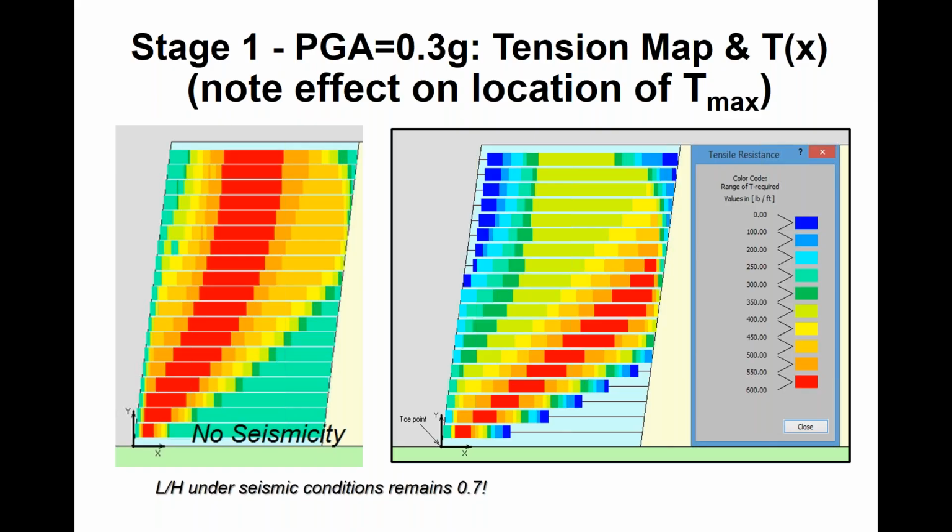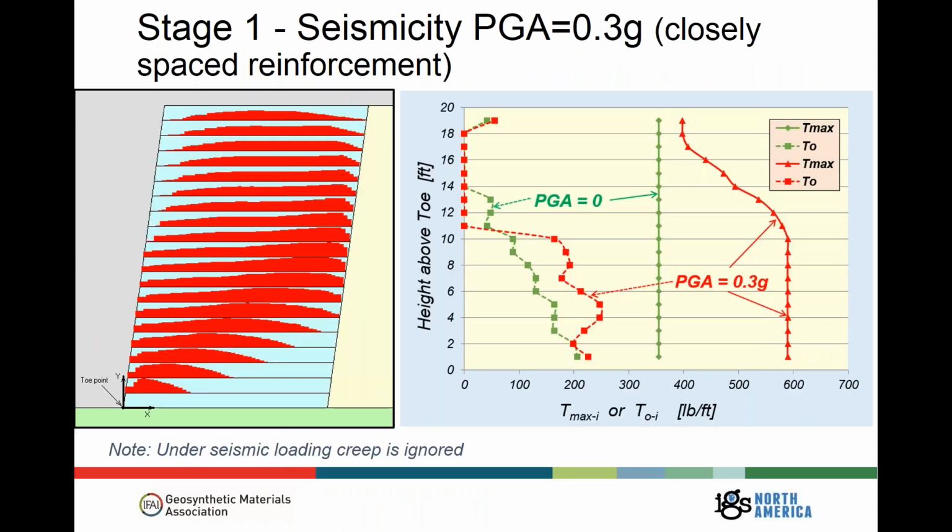And that's really quite important, because in a compound failure, you might not be mobilizing the reinforcement strengths of the upper layers of reinforcements for the critical failure surfaces. There's the baseline solution, that is just tensions in each reinforcement here, and you can see on the left that, again, there's a band that essentially follows all the way to the midpoint of the wall, representative of a compound mechanism. So, in green, let's look at Tmax.